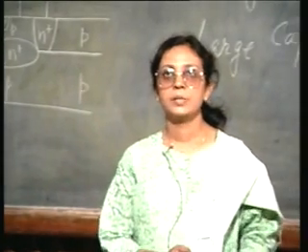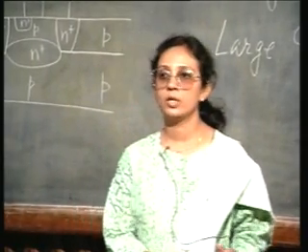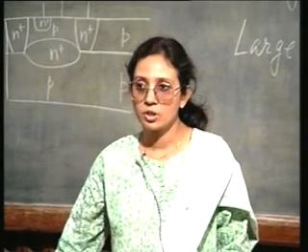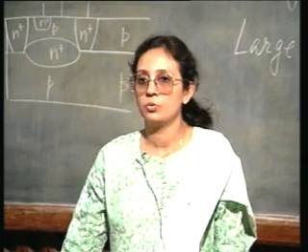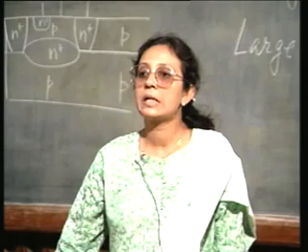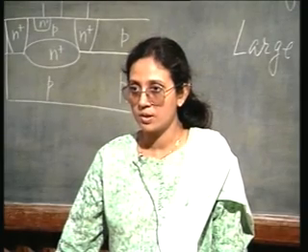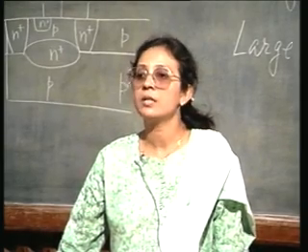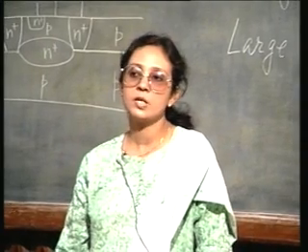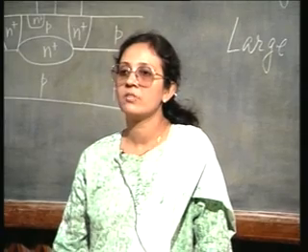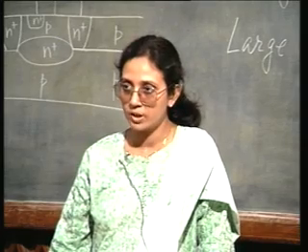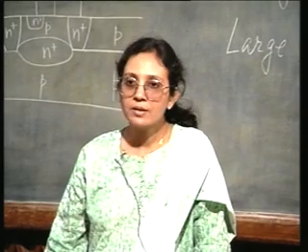But people began to realize more and more that there must be a better alternative to junction isolation. After all, what do we want to do? We want to isolate the two transistors. That means, we do not want any electrical connection between the two transistors. For junction isolation, we are doing it with a reverse biased PN junction, because you know, in a reverse biased PN junction, current does not flow unless you have exceeded the breakdown voltage. Okay. Isn't there a better technique?